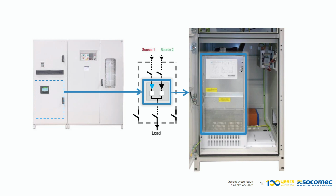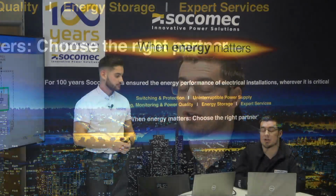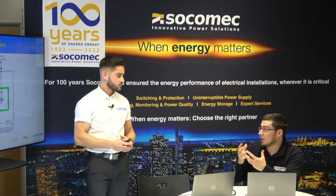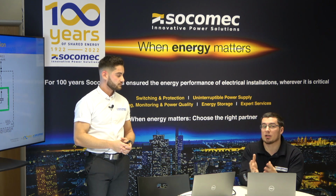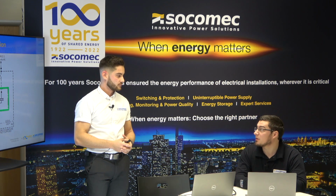And behind the other closed doors will obviously be the switches for the 2 inputs and the output. And it's quite important that we monitor everything. So we monitor the Q50, our Q30 and our inputs, and we can flip the logic as well from normally open to normally closed within the software. So if you're integrating it into an older panel and you've only got a normally closed signal, we can take that and we can still work with it, so it's completely fine.